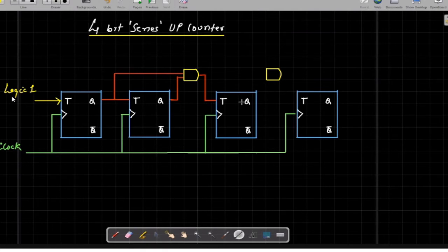Similarly, because two outputs of the previous flip-flop will be available here, and if we want to drive it here, then of course this output will connect to the next flip-flop. All the previous outputs are here and we take one from here, so I'm going to connect in this way, like this. This is one connection, and this is another connection. You can take separately from all the flip-flops, or you can do it in this way, just because the AND gate follows the associative law also, so we can do this connection in this way also.